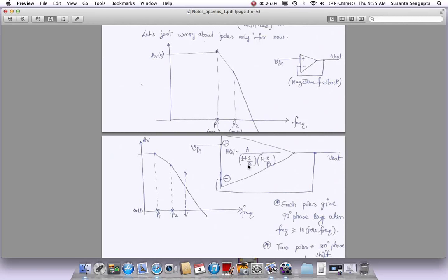On top of that, now what has happened is, as we have got these two poles introduced, each of them adding almost 90 degree phase shift, we get 180 degree phase shift plus another 180 degree phase shift coming from these two poles, with the assumption that P1 and P2 are low poles. Around this frequency where I have the marker, we have already caused an extra 180 degree phase shift because it's two poles. So 180 degree phase shift because it's an inverting terminal plus another 180 degree lag, total it will become 360 degrees, which is 0 degrees. So even though this is a negative feedback system, going through this op-amp, you're going to suffer phase lags because of the poles.